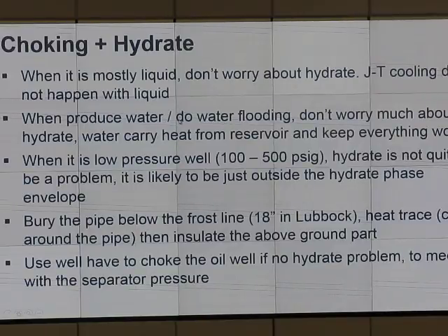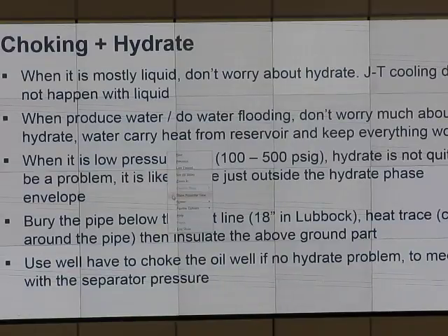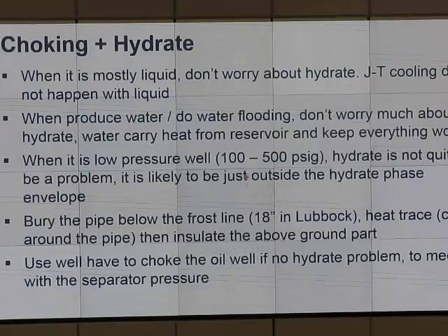When we produce any water or do water flooding, you don't worry much about hydrate either. Water carries more heat than oil, and when it goes through any restriction, it doesn't do any JT cooling. When it is already a low pressure well, you don't worry about hydrate because you're probably outside the hydrate envelope.